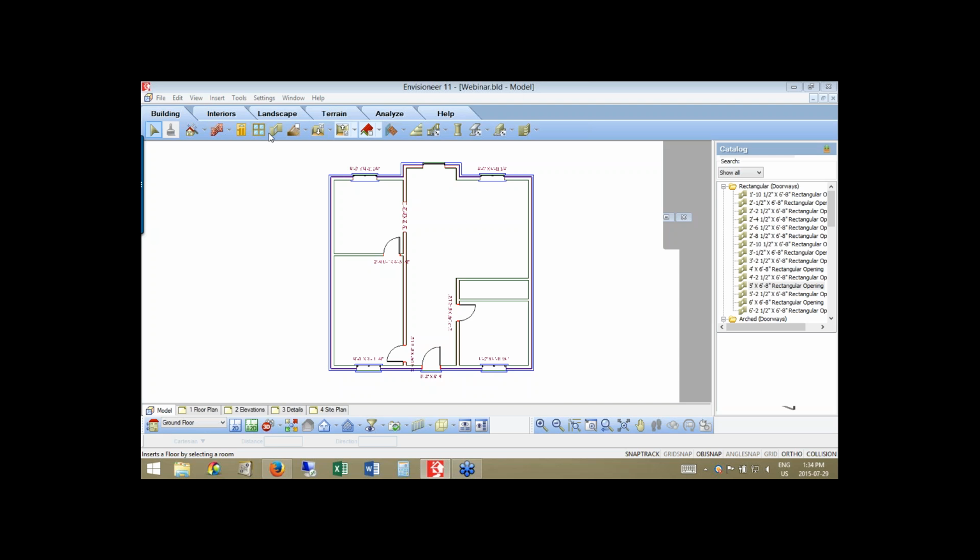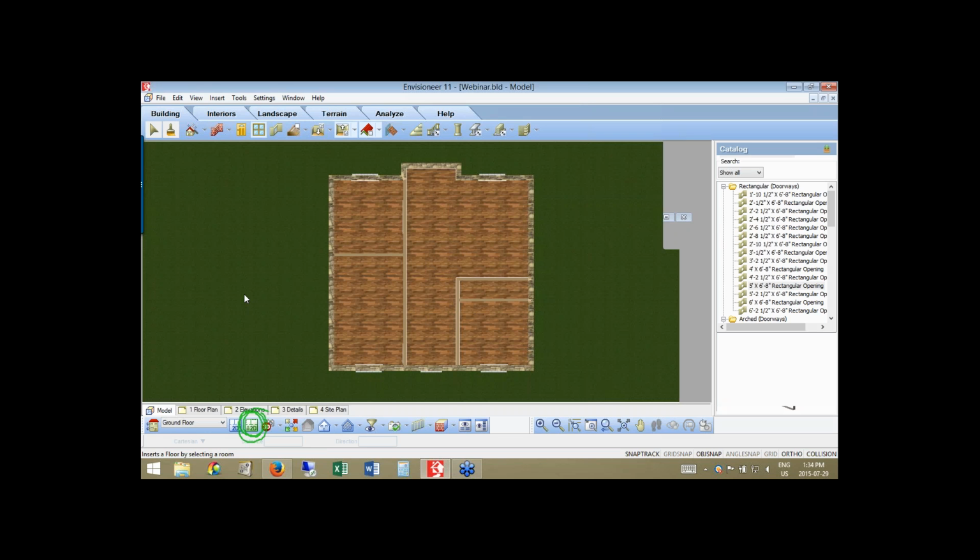From here, the next thing I want to do, designing this out, I might want to show this to a client, is worry about the finishes. So I'm just going to put it into a 2D designer's view. So that's this 2D down here in the lower left-hand corner of your screen. That's green, 2D designer's view. This type of view allows you to look at your model, still looking top-down in a floor plan type of view, but it's also showing you the finished materials that it's going to be putting down as well.